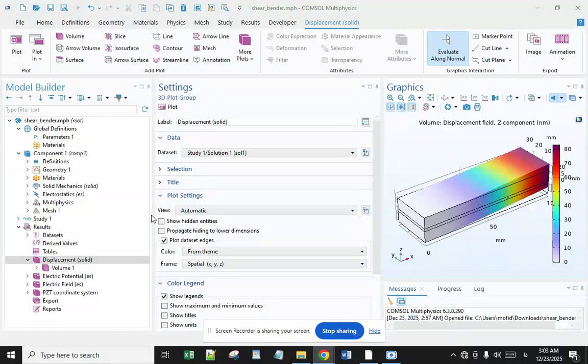Although mentioned early in the 1980s, shear-based actuators were proposed only recently through a preliminary study with a commercial finite element analysis code and a theoretical model. A finite element model was also proposed by Benjeddou and his colleagues and used to compare both extension and shear actuation mechanisms. These theoretical and numerical models use the stress-induced piezoelectric coupling constant e15 of an axially poled piezoelectric layer patched or sandwiched between thin elastic layers.